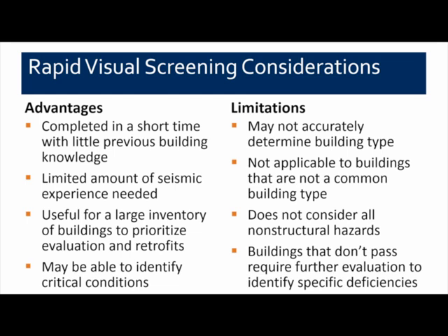This rapid visual screening considers some non-structural hazards, but not all of them because you're not going in the building and you're not looking at a lot of the interior non-structural hazards. So the non-structural hazard evaluation is very limited. And buildings that don't pass this screening require some additional evaluation in order to figure out what the real hazards are and what would be needed to fix them.